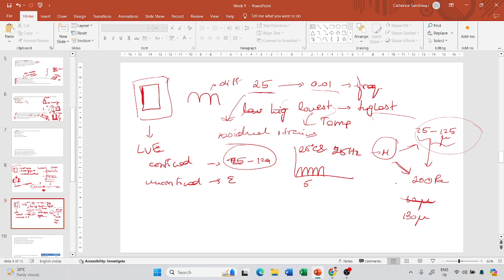So it will decrease the stress. It knows that the modulus that I gave is wrong. From this it will compute the modulus of the material, and based on this modulus, it will reduce the stress such that the strain again falls in this range of 75 to 120. Now it has reduced the stress, and again it will apply five cycles. These are called conditioning cycles, and after that it will apply 10 more cycles. These 10 cycles only it will take for calculations or analysis.